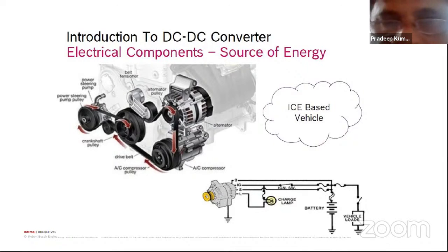But for the IC engine, the torque speed characteristics is completely different. You don't get a high starting torque. So with the electric vehicle, the moment you start, you are getting a very high torque. So you can really go with high power right from the beginning. So the user will definitely enjoy this.